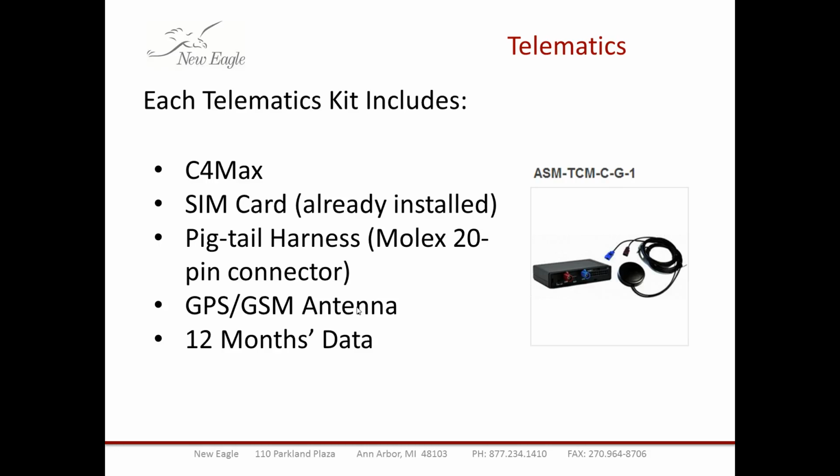So let's say that you're going to get your first kit, when it comes shipped to you, how do you get it set up to run the example that we're just showing? Say you've got a model and you've got a DBC file and you want to select some of the signals from a DBC file. When the kit arrives to you, what do you have to do? So if you've pre-ordered a pigtail harness with the correct connection, you can just plug it in, power it up, and before we ship the device, we'll provision it in the web portal that I was looking at before.